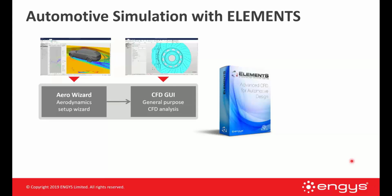Next, we have the general CFD GUI. So this is a general purpose CFD analysis tool. It goes beyond just external aero to do things like conjugate heat transfer. There's some multi-phase capability. There's other types of CFD that we may be doing within our automotive simulation teams. The actual core behind it, so the solvers, the mesher, the utility, is all open source. So this is how we're able to deliver a solution that doesn't have parallel licensing limitations.